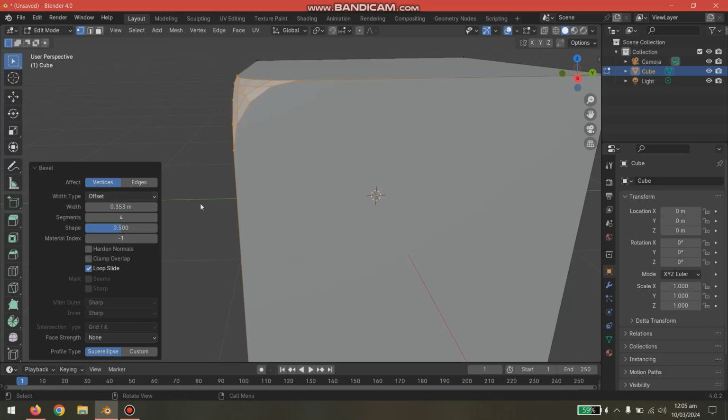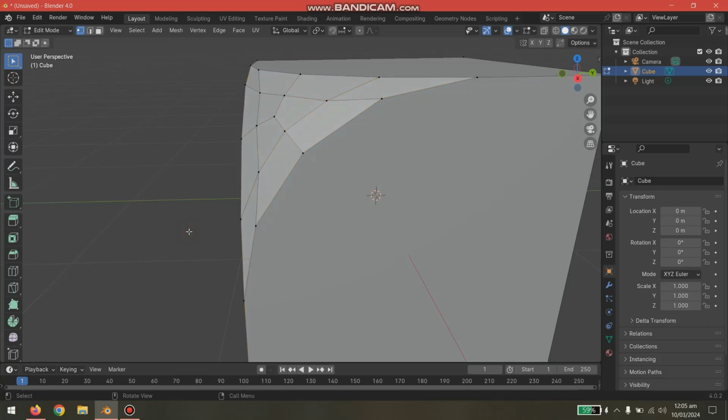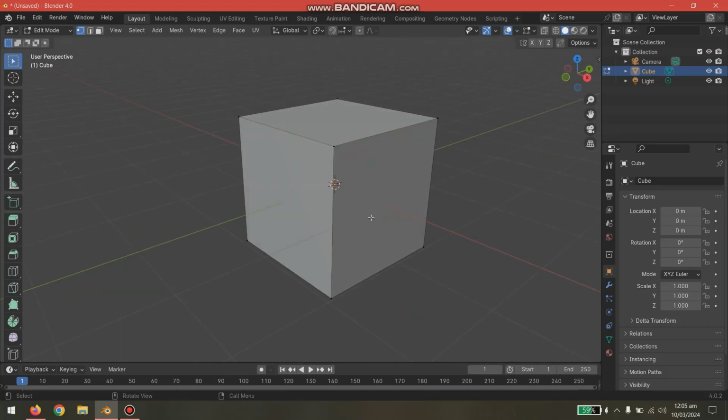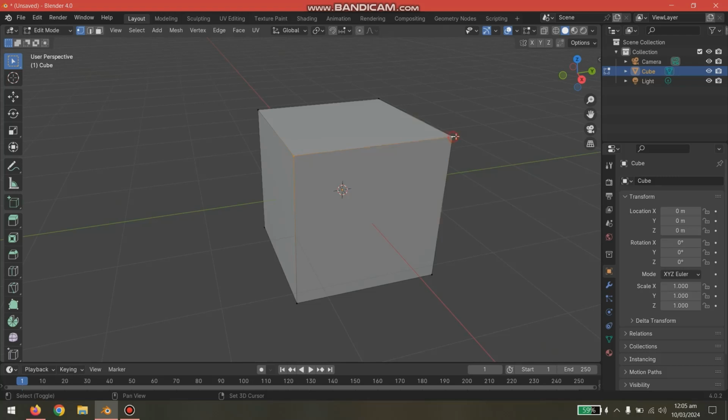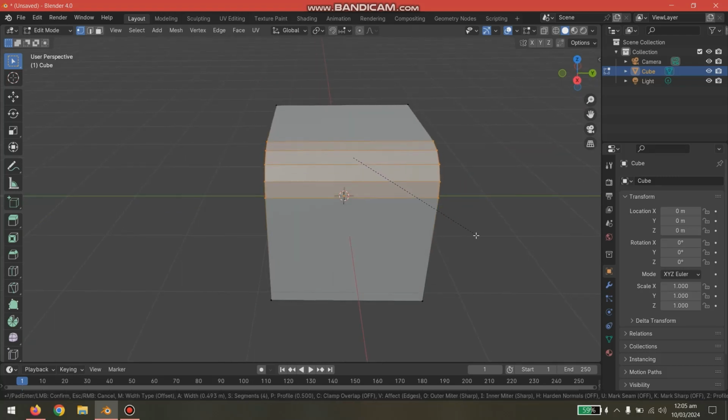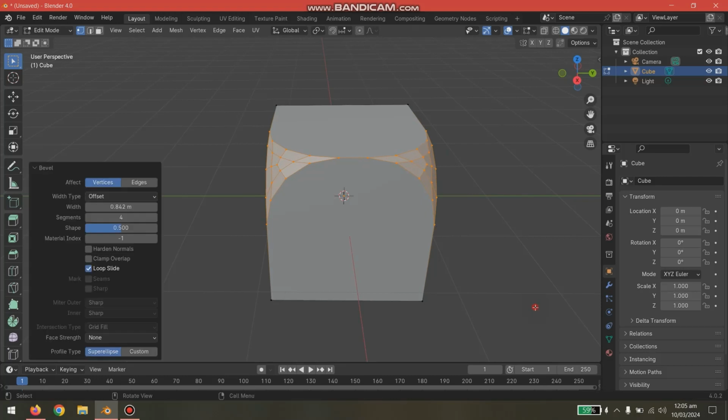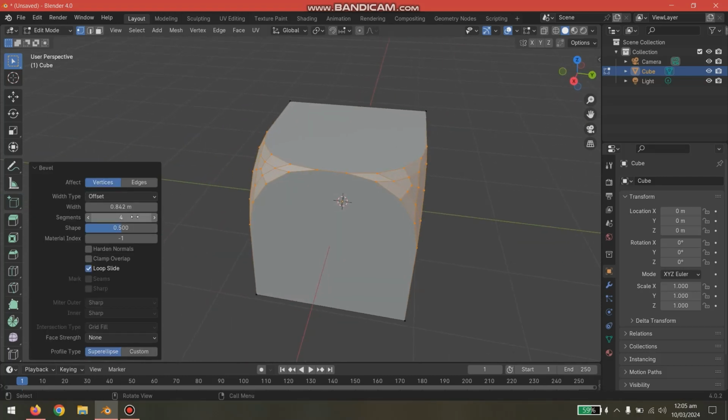Your system might overheat or hang. So you can increase the width. That is another thing that you can do. Okay. So the other thing you can do, you select two vertices and do it again, and you can see here that now it will be applied to both, because last time whatever setting you set is now the default setting. If you want to revert the number of segments and values to the default, just set reset to default. Now it's on 0. So press Ctrl Shift B again, cut it, and use the number of segments.